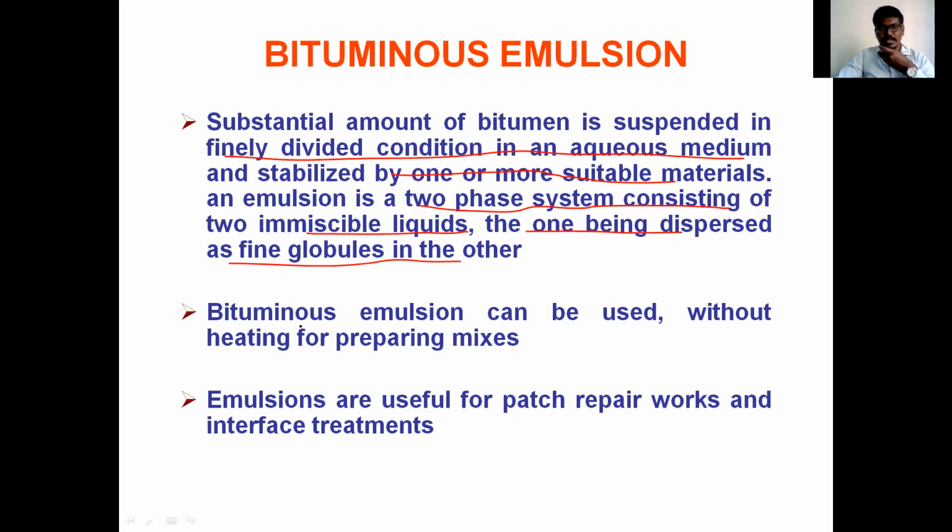So these bitumen emulsions can be used without heating for preparing the mixes. You can use these bitumen emulsions with the aggregates also. You can use the bitumen directly, or you can take the cutback bitumen also. Emulsions are useful mainly for patch repair works and interface treatments.